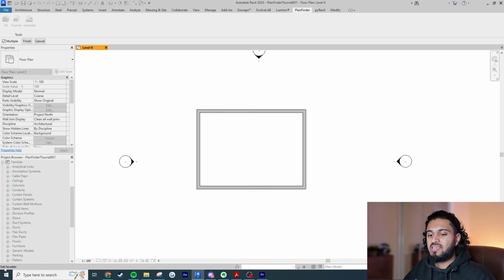And now you can see it says get facades. Now I need to click on the walls that are going to be the facade of the buildings, or where the windows are going to be hosted, so we have some light fenestration. Because this plugin is using machine learning, it's going to position stuff like the kitchen, the dining space, the bedrooms closer to the spaces that require light, and stuff like toilets or storage further away from it, just because this is made to be suited to regs, right? So it's actually kind of useful.